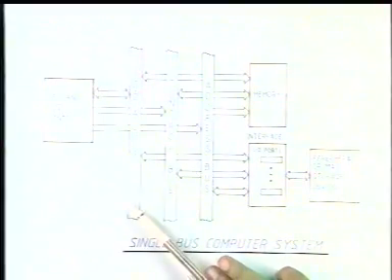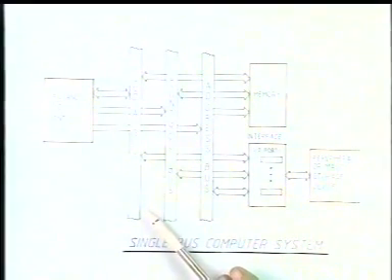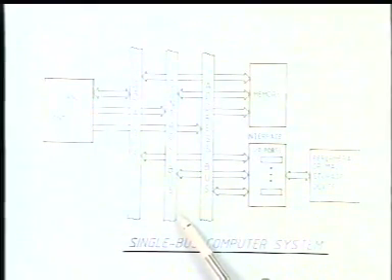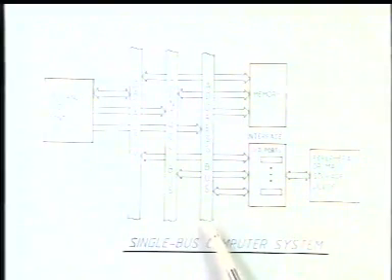And the address bus, as discussed, is normally a unidirectional bus. And the data bus, because the CPU has to read as well as write, has to be bidirectional. Now, the control lines are basically to decide whether the data is for the memory or for the input-output devices. Because it is a single bus computer, there must be a different method to differentiate, or different control signals should be available, which will tell you when to access the memory and how to connect the peripheral devices.